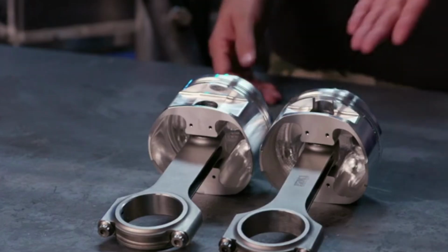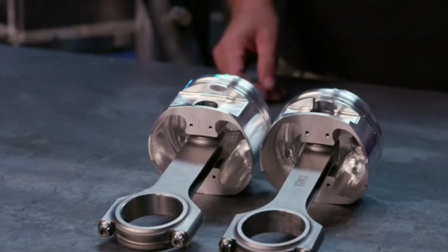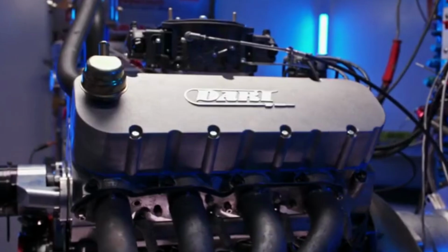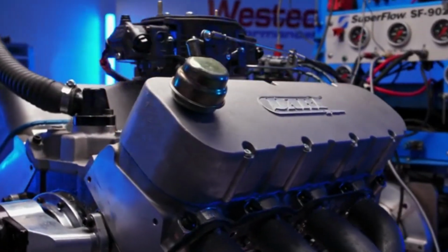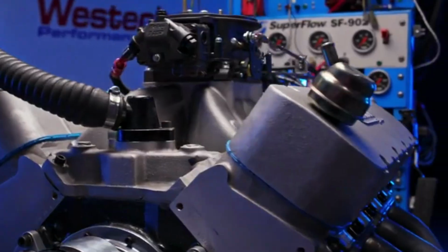Basically, we're starting with a big block Chevy platform, but we are using a Dart aftermarket block. And because I wanted to test two radically different lengths of rods, I mean, there's a difference of more than 5/8 of an inch here, I had to do the math to figure out the engine that would take the biggest difference. And this is what I figured out. From 6.135, which is, by the way, a stock rod length on a big block Chevy, all the way to 6.800, which is really big, required a very short stroke crankshaft. So this thing begins with a crank that has a stroke of 3.76 inches. It's like a stock 396 or 427 crank.